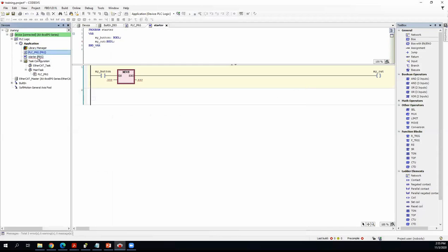So yeah, we created two programs, and if you joined the PLC training, we said that there are different programs, but the execution time can be different. So it's the same for CODESYS. You can define the execution time for each program separately. It's called task configuration. Inside the task configuration, you define which program needs to be executed and when. For now, for instance, there are 2 tasks. You can create more than 1 task.